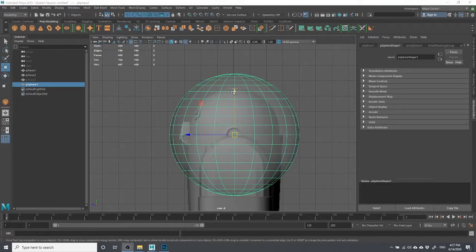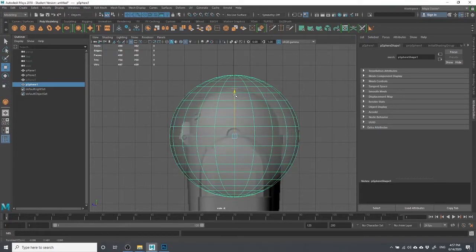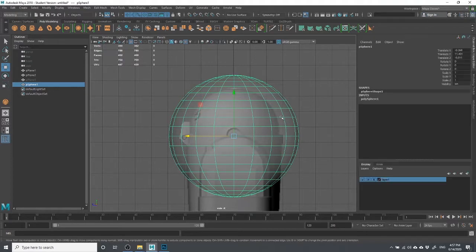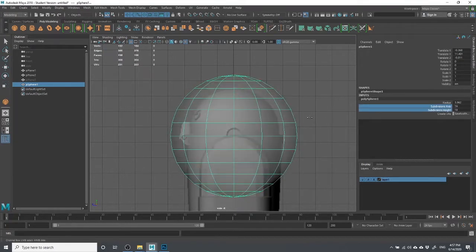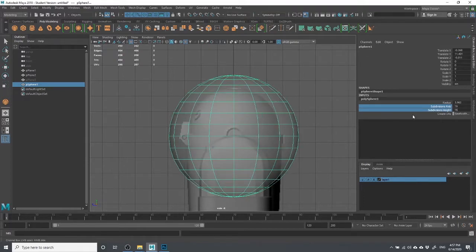So here I've pretty much just centered that sphere to the center of that sort of hinge. Let's call it a hinge. And I'm just going to put that right about there, and we can further adjust the size of this dome here this way. So right now I find that maybe these 20 sides, maybe that's a little much. Let's have that be 16.